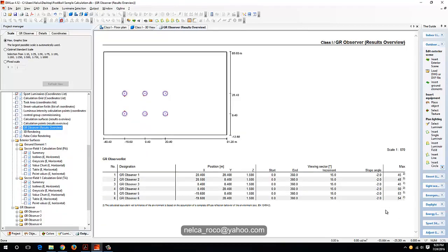To remove that, either you increase again the height of the fitting, the height of the pole, or select other fittings that have lesser glare. But if it's a floodlight, it's usually like that. So to remove that glary part, you need to tilt the floodlights downward more, or adjust the height of the pole.